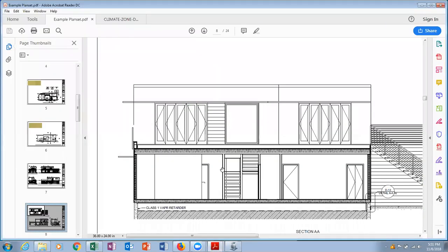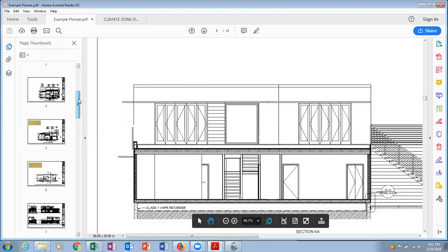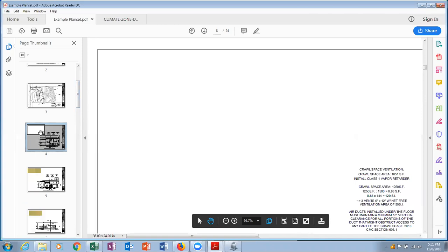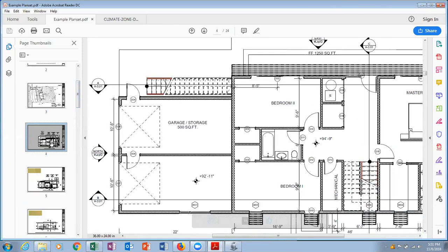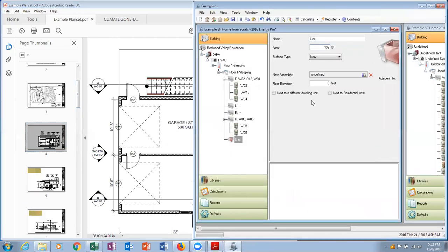And I'm going to open up the plan set just to visualize what we're doing here. This is connected to the garage. So this is why we have 22 square feet of wall area that's open to the exterior behind it. And then the rest of that left facing wall has the garage behind it. So it's considered an unconditioned space behind it, and it's going to model differently. So the left interior to the garage is what this is.